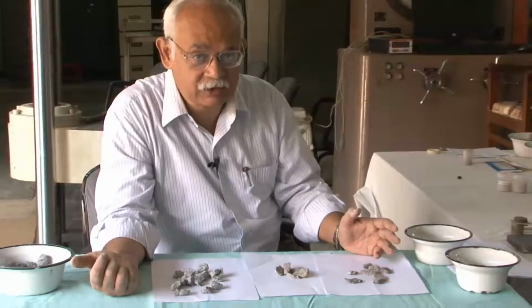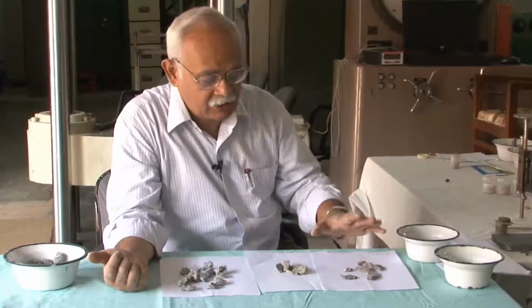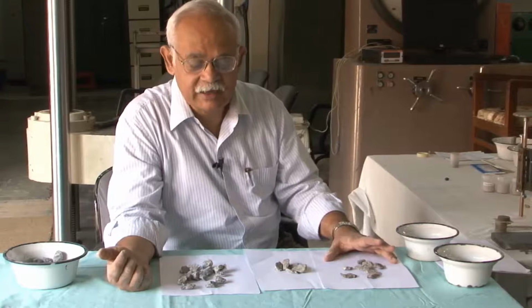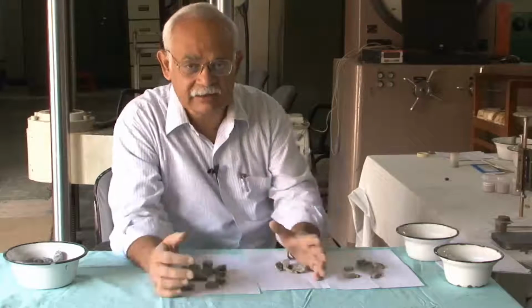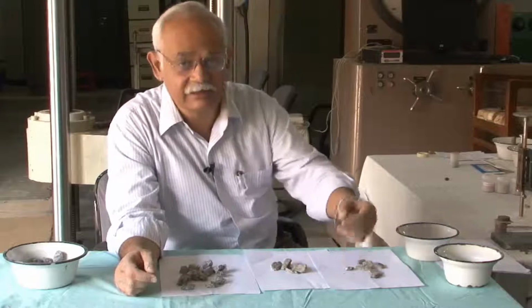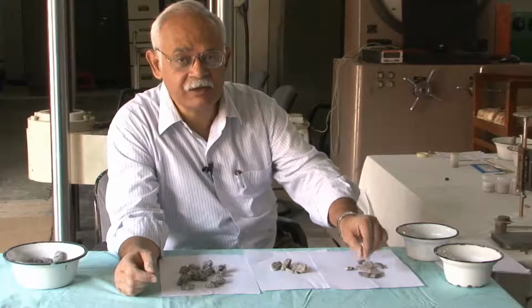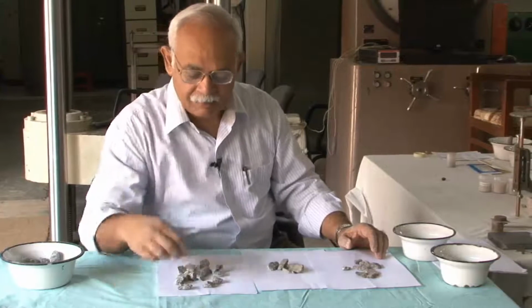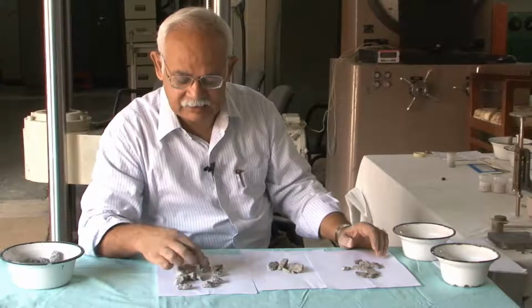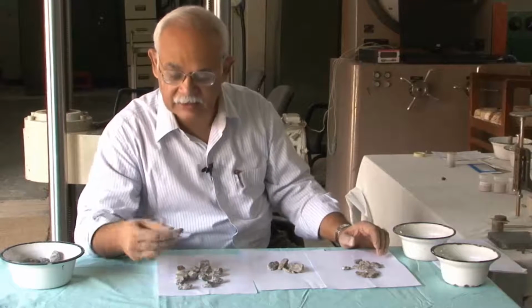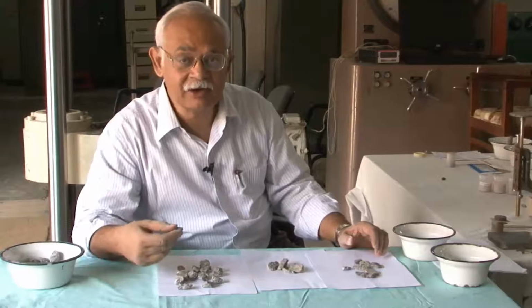They should not be used in concrete construction. We cannot avoid them, and therefore, usually what the specifications say is that once we have an aggregate sample, we determine the elongation index and the flakiness index, and it should be within a certain permissible number. We may mix some of these aggregates which could be elongated or perhaps flaky, something like this, but there should not be too many of them.